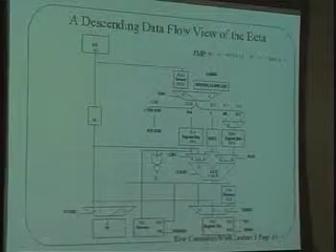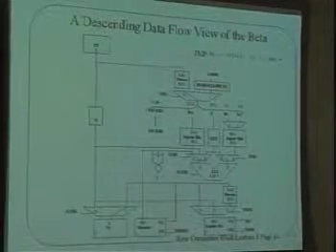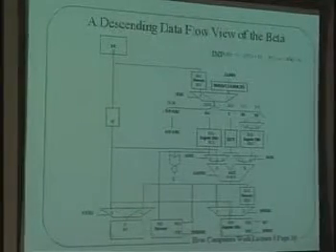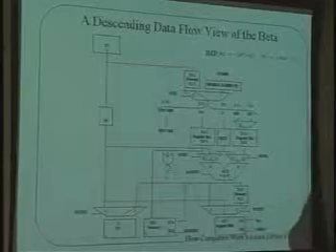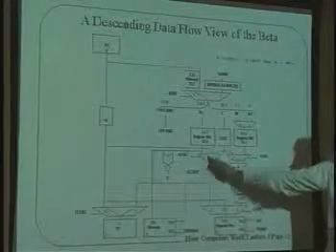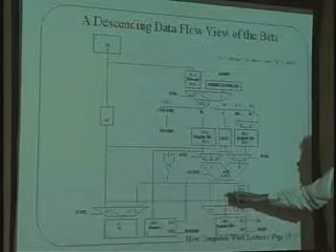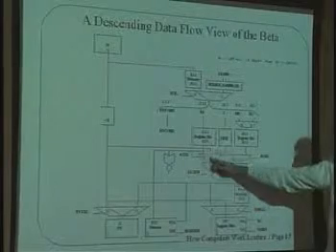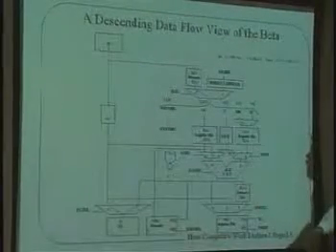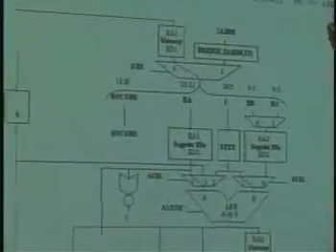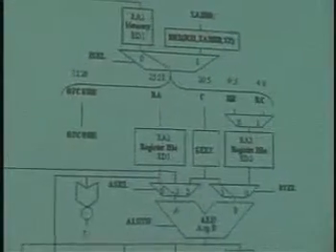Okay. A jump. A jump is very similar to a branch. Let me go back and forth here. What is going to change? Isn't this cool? I'm sorry you can't see it, but anyway, this red shifts from here to here. Well, you can at least see these things moving, right? Yes, I can. Okay. And so instead of saying that we're going to take the PC plus 1 and add C to it, what are we going to do? We're going to take the contents of RA and add C to it. And that's what jumps do, right? Contents of RA plus C goes into the PC.